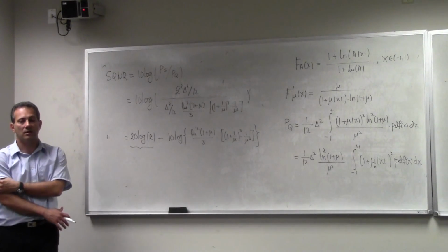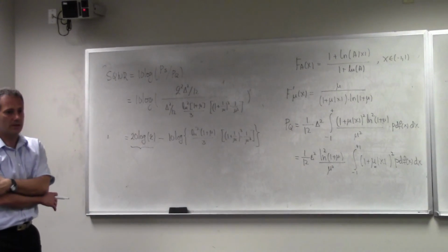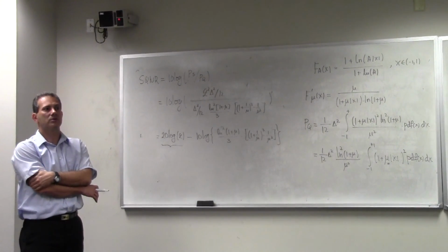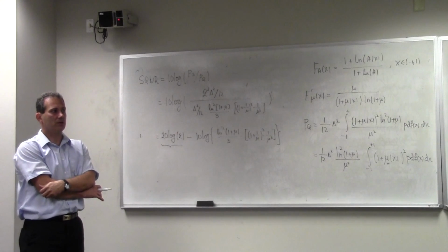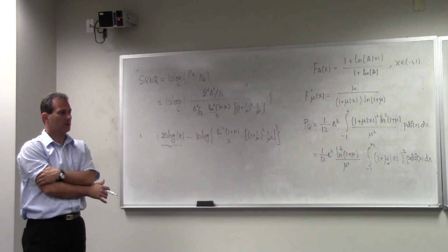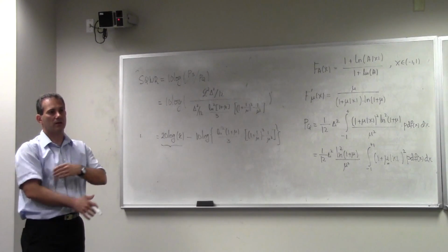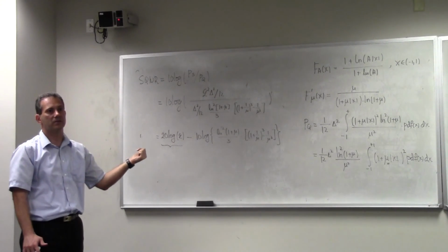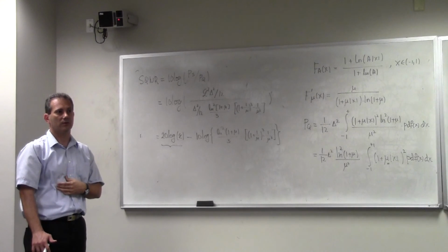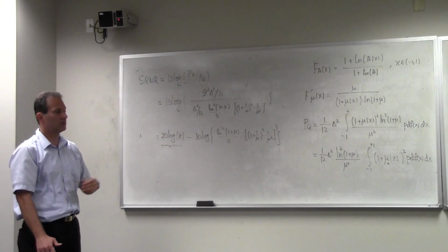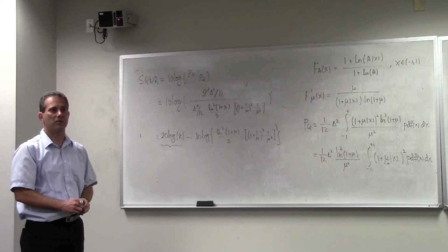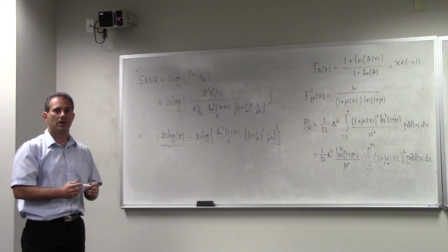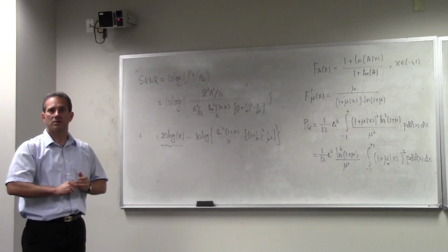This is why, if you don't do any compression and you try to quantize the signal, the number of bits that you need is, I believe, 10 or 12. And then when you use this compression, you can go back to 8 bits and still get a sufficient quality of the signal, so that it's imperceptible to us that it has been quantized and reconstructed back. Okay? Any questions?